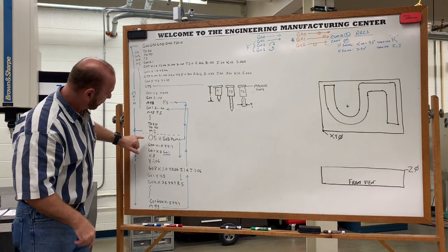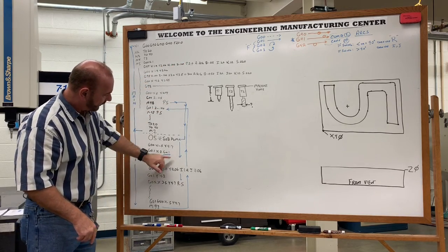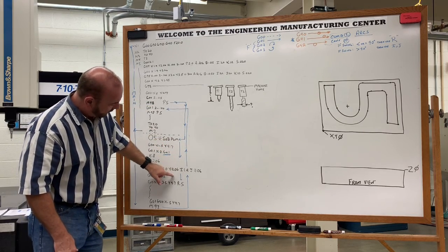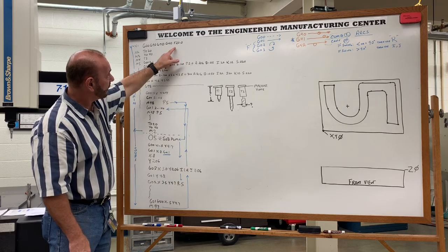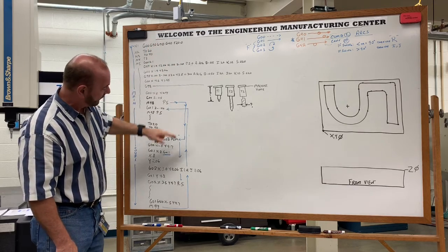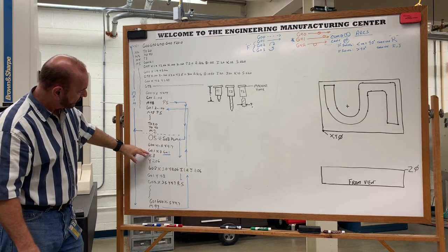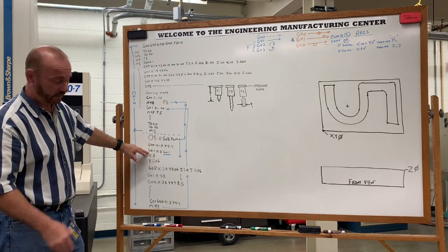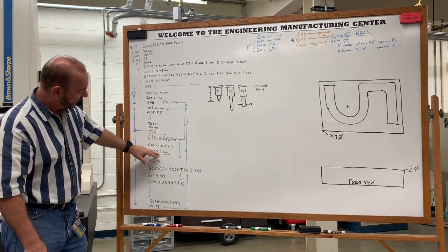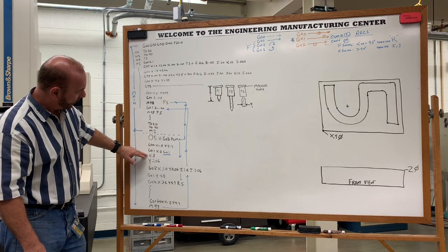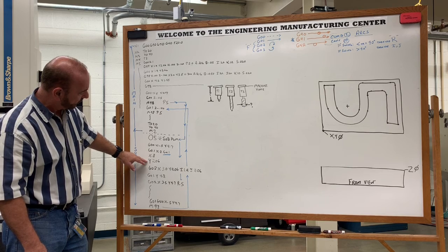If you notice here, in this subprogram, when Harry was writing this shape, he does not include any F statements. He has an F statement up here, so once that switch was turned on, he did not have to repeat the F statement. And here's another move where the G01, a linear move, was actually turned on, and it moved to an X.3 dimension, or position, and then it went to X.8 and then Y2.06.